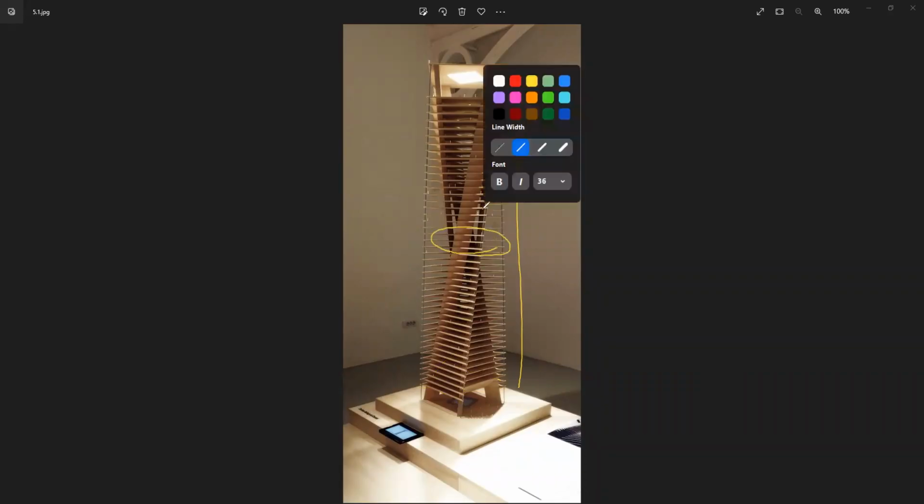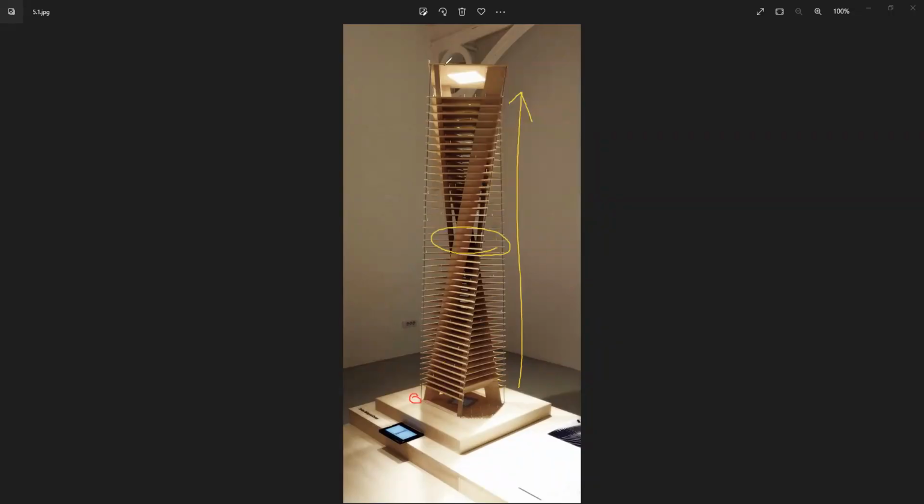You can also see a rotation done. There is a 90-degree rotation, like this is the initial position, and at the last floor plate, it has moved to 90 degrees. So there is also a rotate used here. I don't think they've used a loft. They have just created floor plates with boundary surfaces. And also the detailing is interesting. You can see the floor plates are for the initial moved curves. Initially, when you move, you get the same size floor plates throughout. So that's like the moved curves. And then the loft is done for the final lofted, rotated geometry. So this detailing is also something I found interesting.